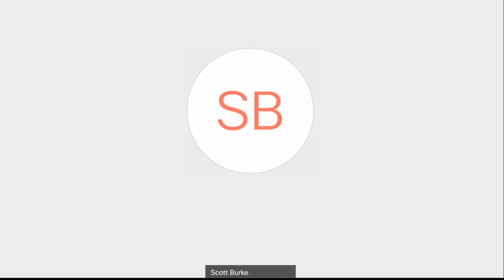So another question here, are there best practice suggestions for setting up a folder structure in BIM 360 Docs? And not really. I mean, other than the way you're setting it up now to work internally. In this case, because you can work with external consultants, it's really simply about having one folder per design team. I think that's really the best way to do it. Where you put that folder and how far down in the system you want is up to you. I always want to keep folder structures simple and not too complicated and not too deep.